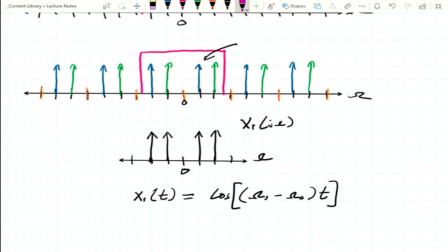The filter, right? So instead of doing a low pass filter in this case, what can we do? Well, we definitely don't want to do a high pass filter, because a high pass filter is going to get all of that stuff. But you said it, right? Yeah, we want to do a bandpass filter. If we knew ahead in advance what our sampling rate was, and what our incoming frequencies were going to be, then yeah, we could create a bandpass filter to lock that guy in.